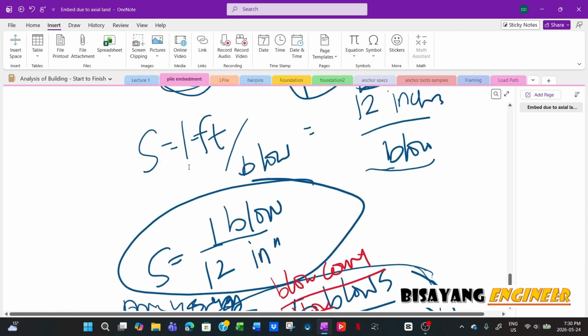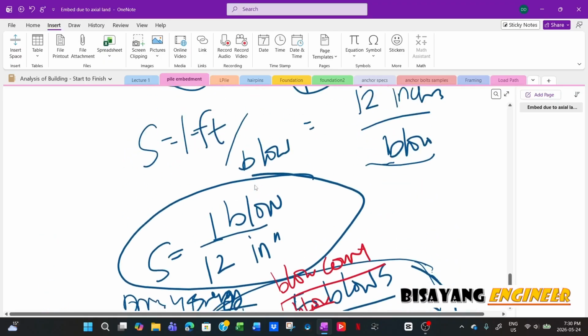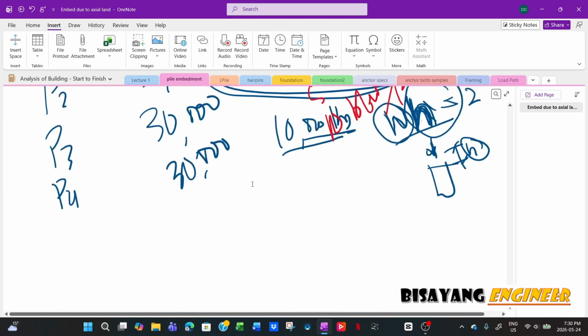But like I said, I've seen a lot of foundation plans where they just specify one criteria, which is drive the pile to refusal. And if that's the case, it's going to be really expensive. If it's just 1, 3 piles, 5 piles, then that's fine. But I've designed a project with almost 2,000 piles in one project, all driven piles.